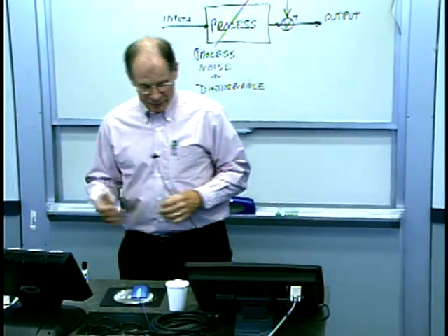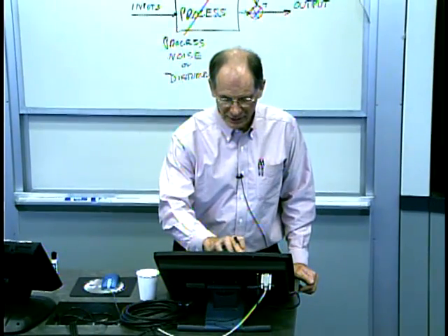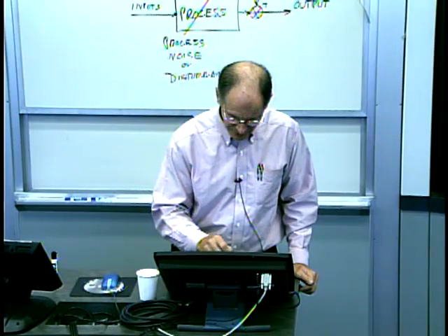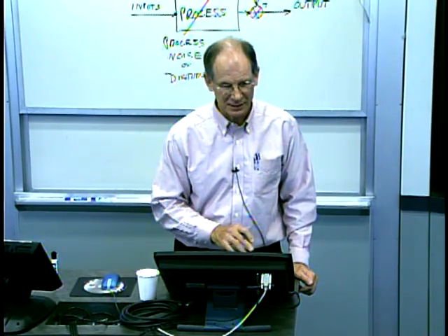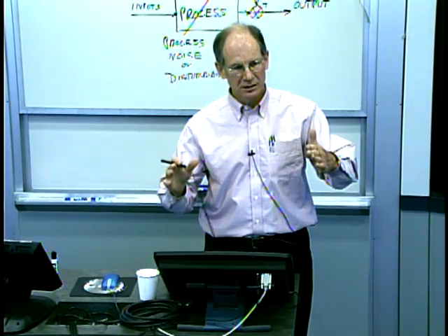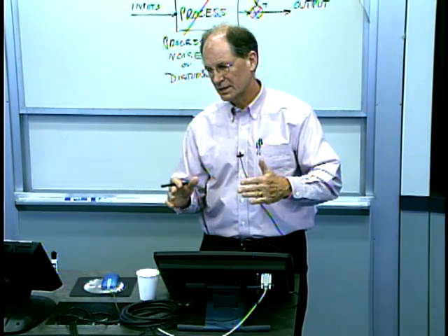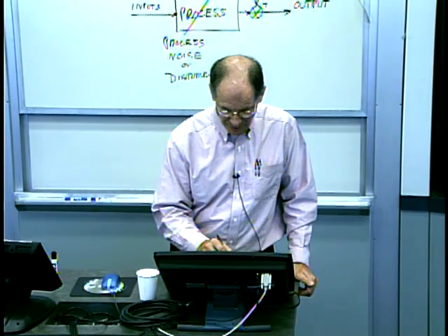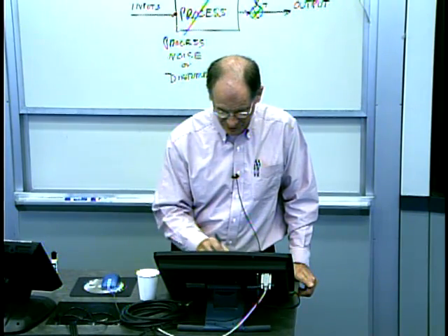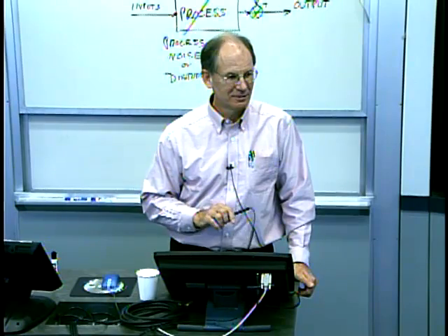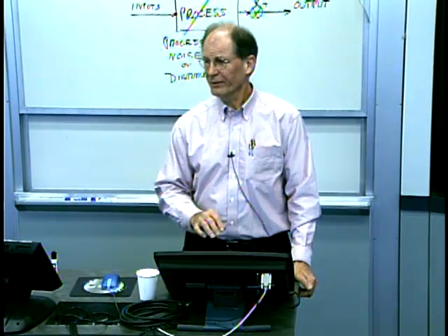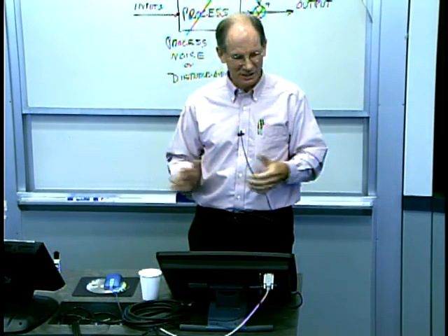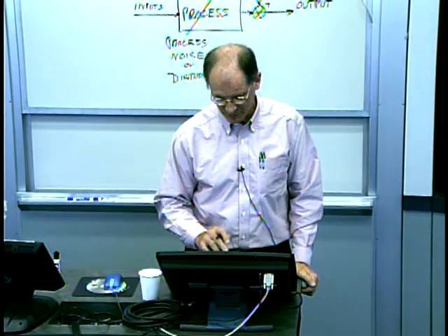So these are some examples of the process being not in a state of statistical control. Now, the other thing, of course, that could be happening here, with the exception of the bimodal thing, is that you've got a normal distribution, but its underlying statistics, the mean and the variance, are no longer constant. The other thing that could be happening is that it's still random, but it's switched its distribution to something like a uniform distribution. The real fact of the matter is that it's probably not following any distribution because it's got a lot of deterministic behavior underneath it.